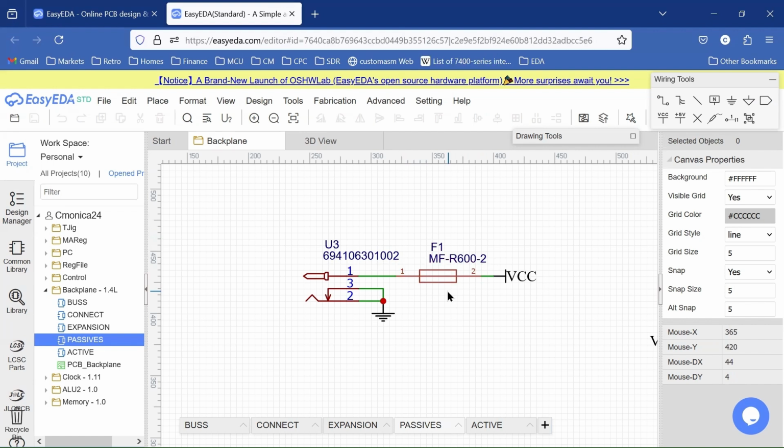So that's one variety of overcurrent, and the more dangerous variety of overcurrent is a short circuit, right? If for some reason we have a failure in a trace, or a failure in a component that results in a direct path to ground, that's going to make the current shoot up really high, and we want to protect from that, because in a situation like that, we could damage a component, or even worse, we could damage a trace, and we don't want that to happen.